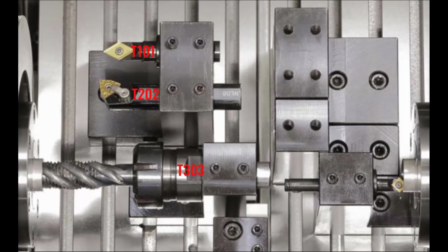We use the tool measure function on the Mitsubishi control to find the exact location of the tool. Pay special attention to the spindle and material clearance of the tools on either side of the target tool. You may have to rearrange the tools a few times before you find the optimum position. Tool number 1 has a different offset on the sub and main spindle side. Some programmers like to use tools starting at number 21 on the sub side, but it's not mandatory. The offsets on the sub side are totally separate.